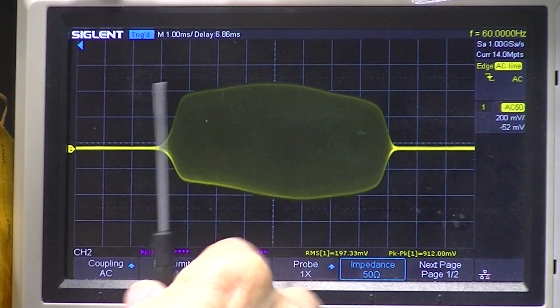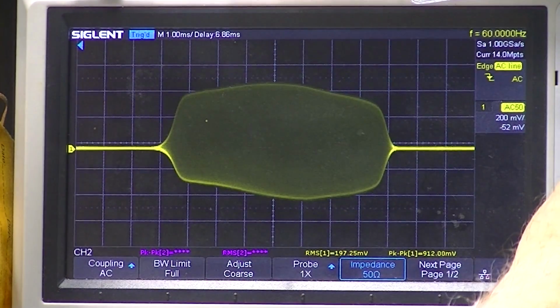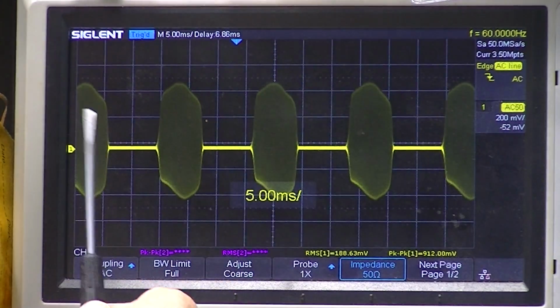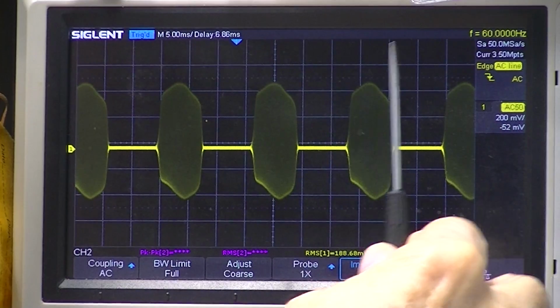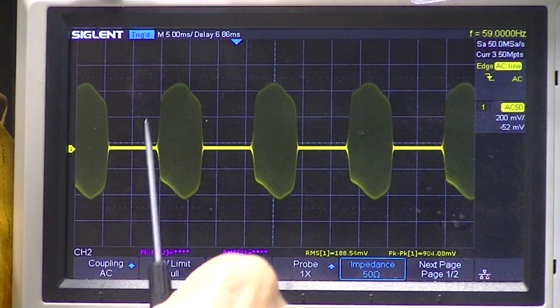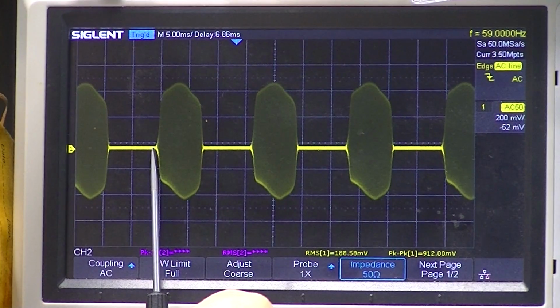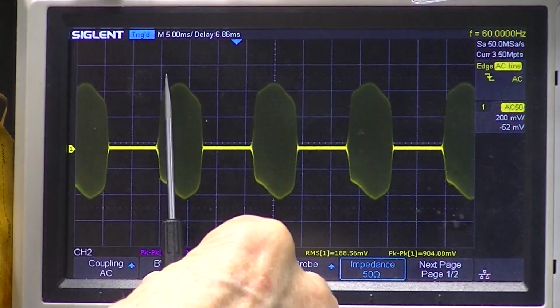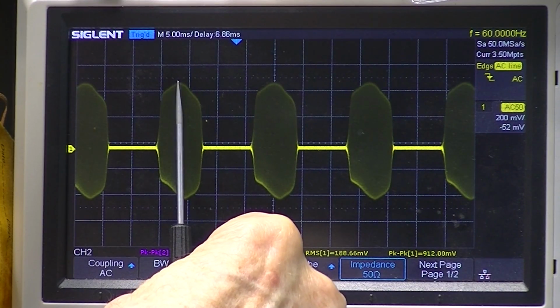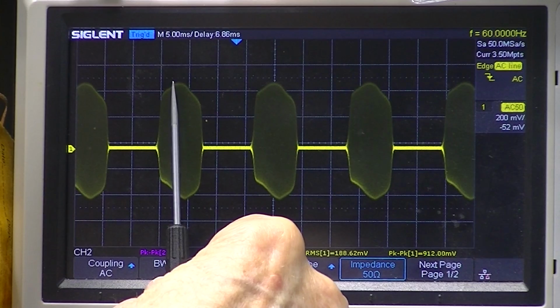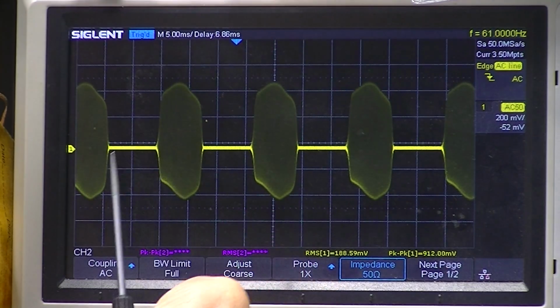So what's happening here is we have an AM signal, it's repetitive, contains an RF inside the envelope, and the RF is varying from some low to some high frequency, with the center frequency being either 10.7 megahertz or 455 kilohertz.